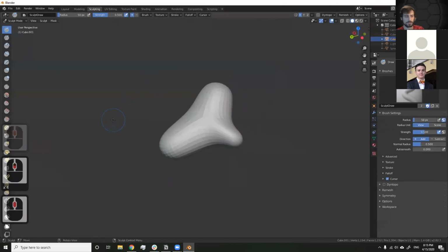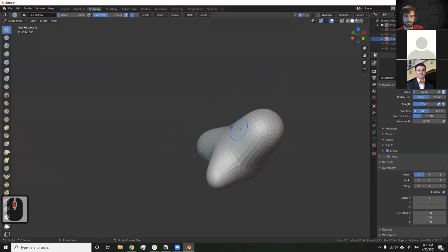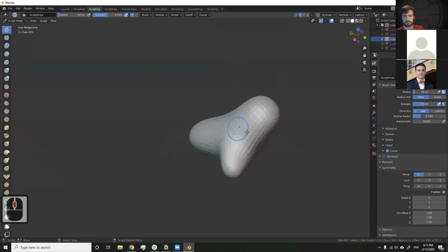So your sculpting layout looks a little bit different than your standard editing layout. You have a bunch of tools along the side still, and then you have more options along the side over here. By default, you're going to be brought into the options menu over here that allows you to do some changes on whatever brush you have selected and then adjust some of your other settings down here. So the first thing that you'll want to adjust is your symmetry option down here. By default, it's going to have the x-axis symmetric. This isn't a symmetric model, so having symmetry on doesn't really make sense, but we'll go ahead and turn it on when we go onto the cube later because the cube is symmetric and it's more helpful there.